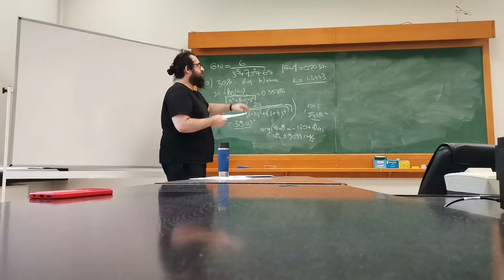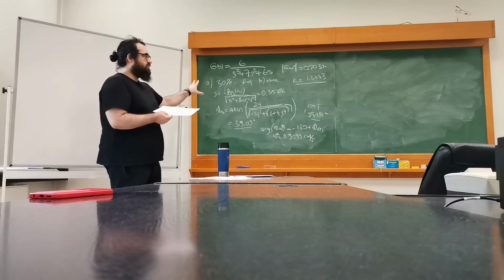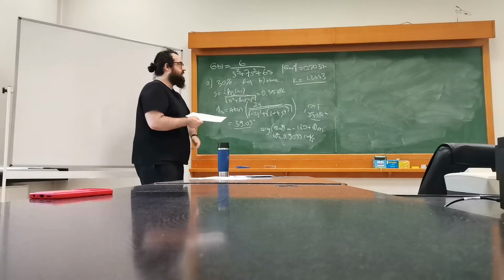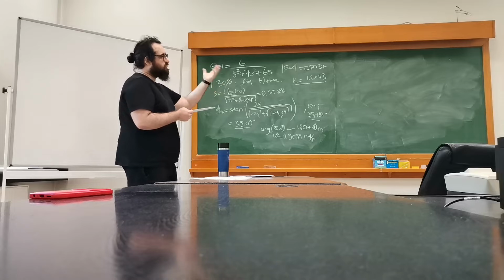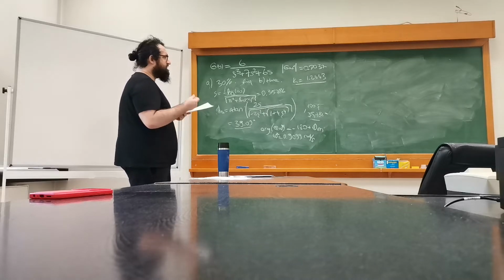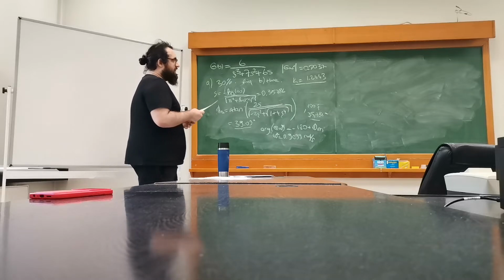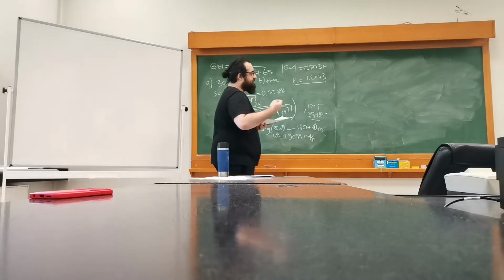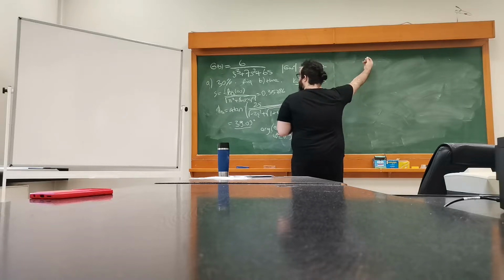We have a third order system that has an extra pole. Therefore, I'm not really sure what the overshoot is, if it's really 30% or something else. Therefore, we have the time domain part. We'll see the actual model behind this design. If you get the same gain value, and if you have a satisfactory dominance factor, we'll see that this will work. If they're a bit different, then we'll see that there is a better solution. But if you're using the frequency domain, you don't have that much choice. So let's look at this.